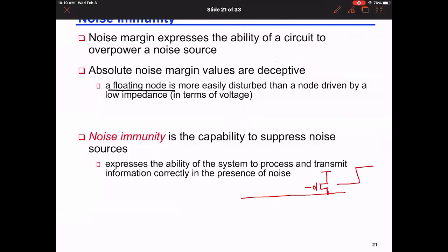And we will study this. And I have some memory design that is connected during this. And let us say that this is the clock cycle. So this is when the clock is on. This memory circuit is supposed to evaluate, and if there is a match, it is supposed to discharge the capacitor. If there is no match, the capacitor will remain high. Simple logic function, forget how it works. We will learn very little basics later.